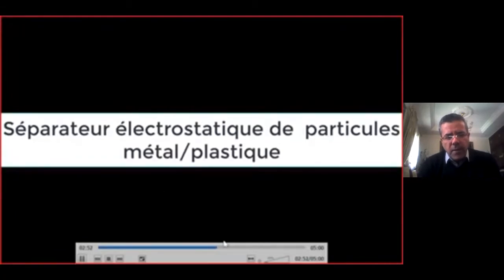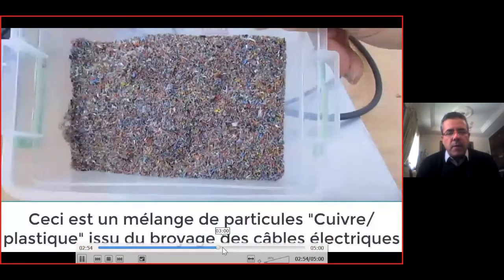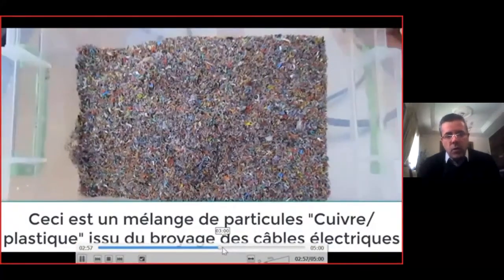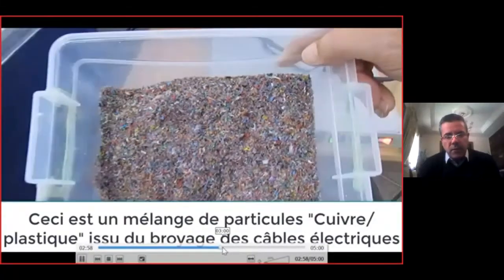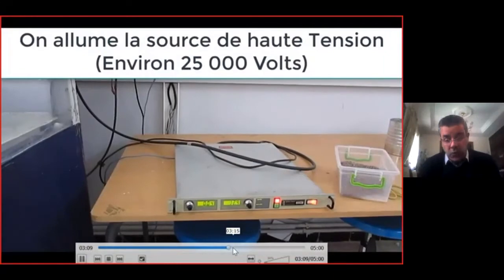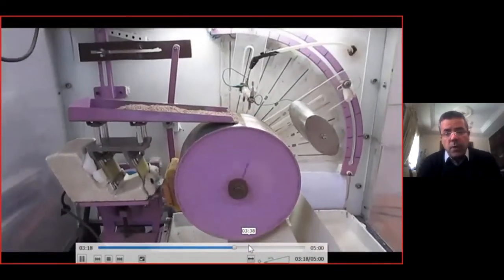The third one is for metal plastic particles. This is for recycling, for example, electric cables. This is a mixture of metal plastic particles. We put these on the vibratory feeder. This is a high voltage power supply, 20 kilovolt. The vibratory feeder is put on the rotating cylinder.